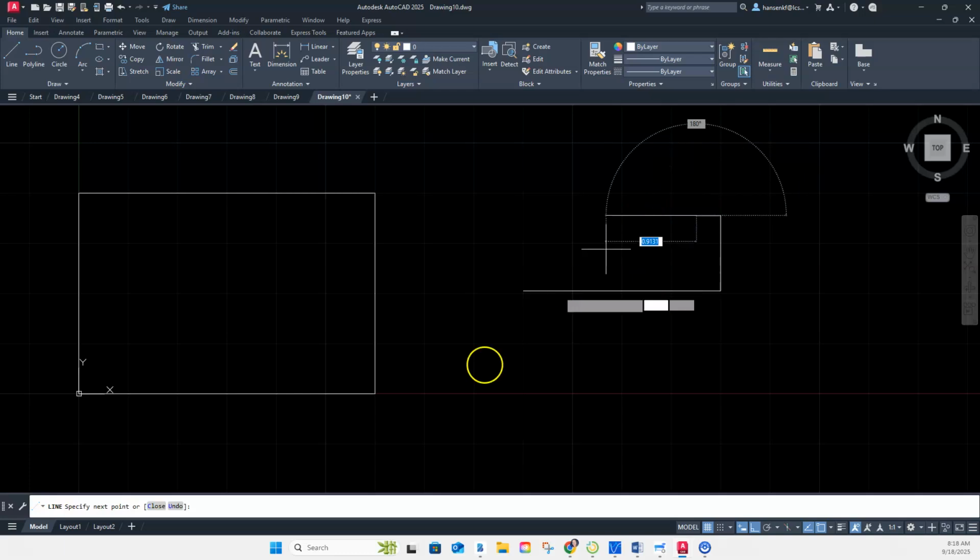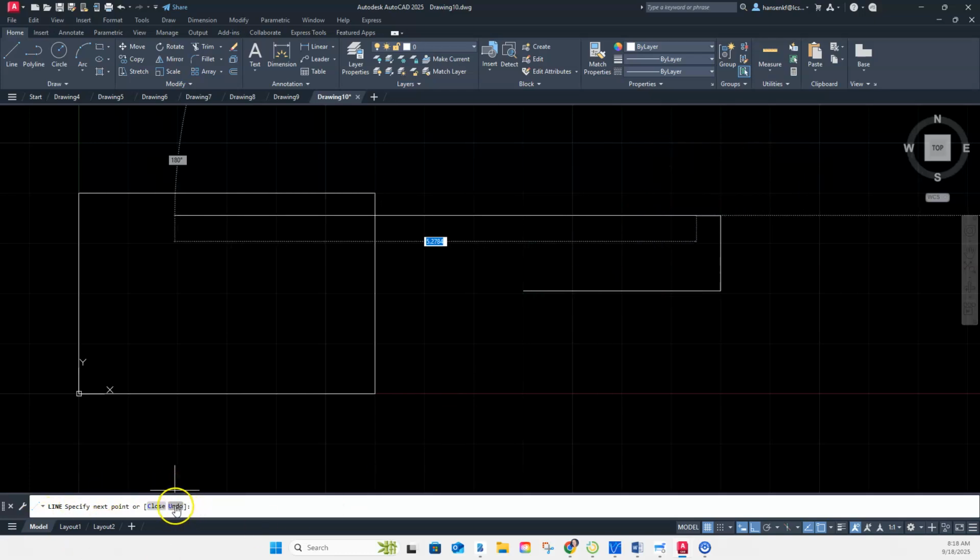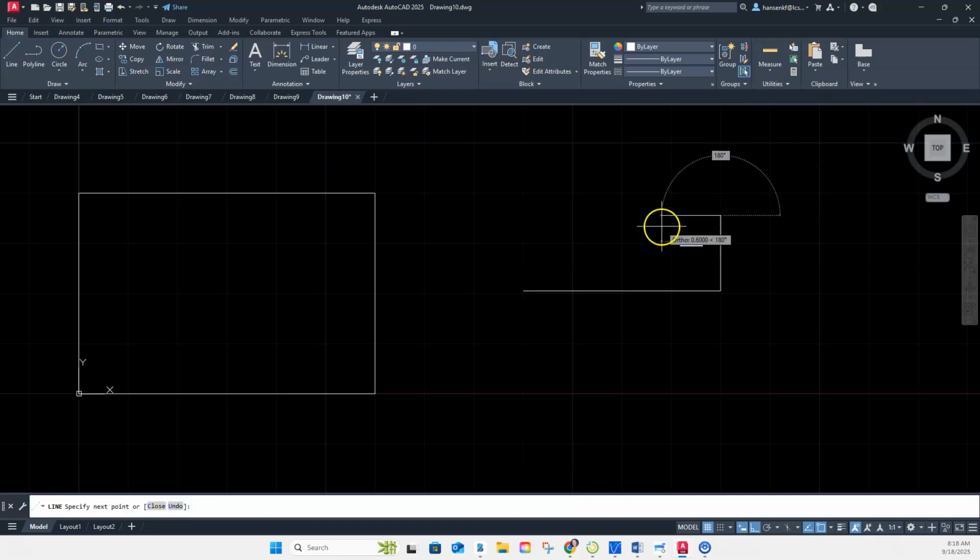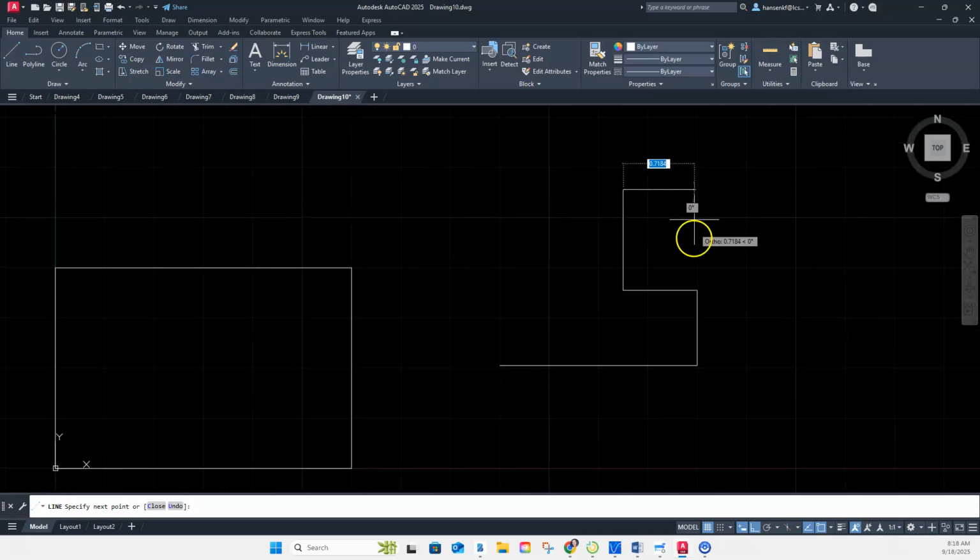If you mess up, you can always hit the undo button. Okay, and you can type in a different value. And it's pretty easy to just follow a lot of your geometry. If you don't want to look up the dimension that you had and you're trying to follow something that you already have, it does have the availability to line up. Oh, wait, maybe I don't have my tracking on. There we go. So you can point to an existing object and line up. And so it's seeing that it's 0.75, so I can just hit the enter button.